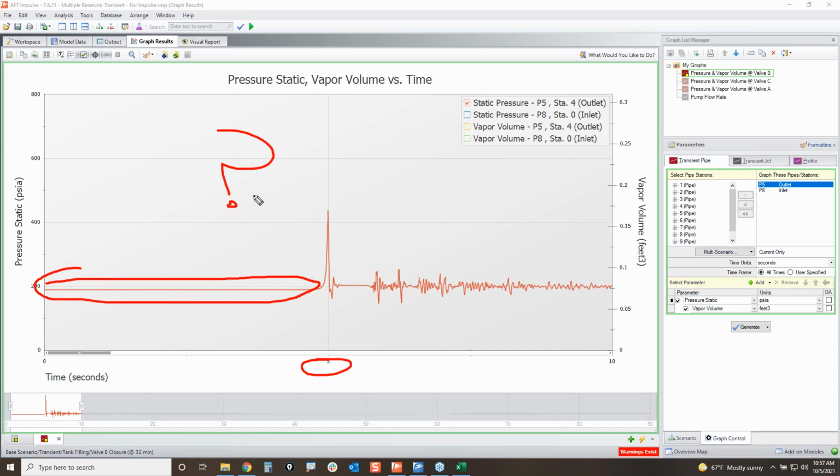This particular valve, when I was closing it linearly in 5 seconds, is not going to make an impact on flows, pressures, velocities in the system at all until the very last few open percentage values of the valve closure. So even though we're closing this in 5 seconds, nothing happens until maybe 4.9 seconds.